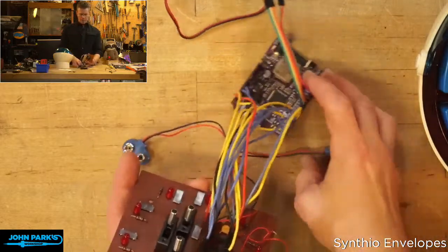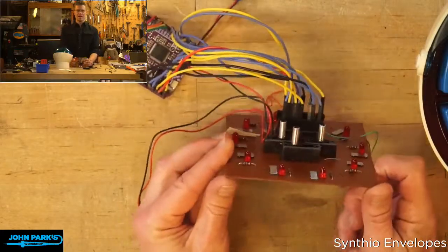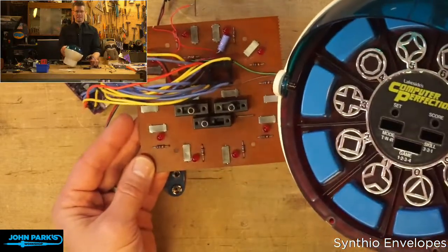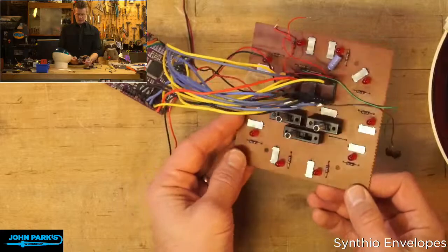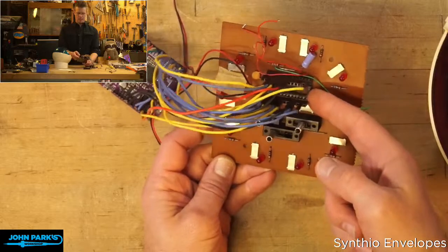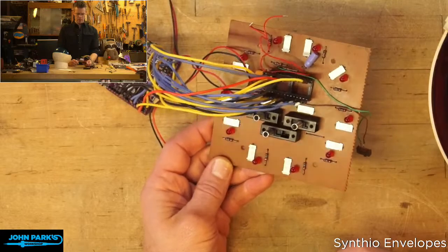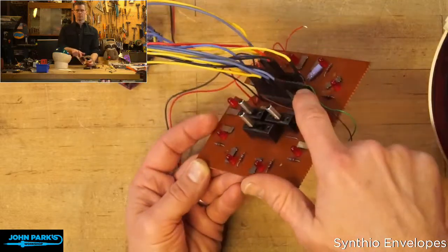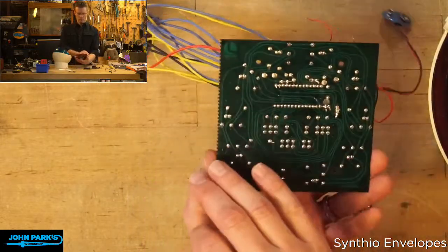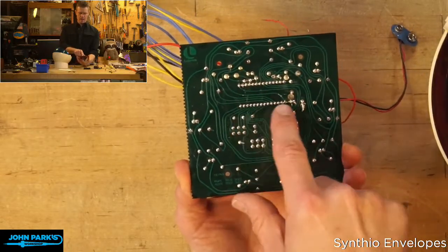So one of the things as I'm progressing with this that I've got to do is get all of that mess out of the way, because it needs to get mounted back into there. It was nice and convenient to use that dip socket that was there, but I really don't have a lot of clearance. So either I could do some very short right angle headers in here, or what I'm thinking of doing is actually desoldering and using these pads from the back side.